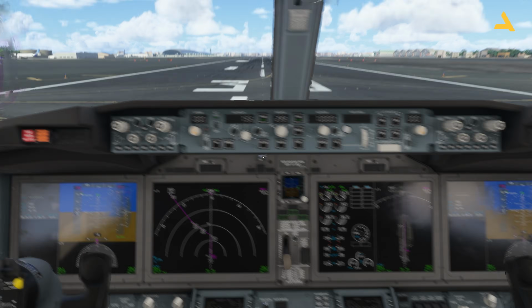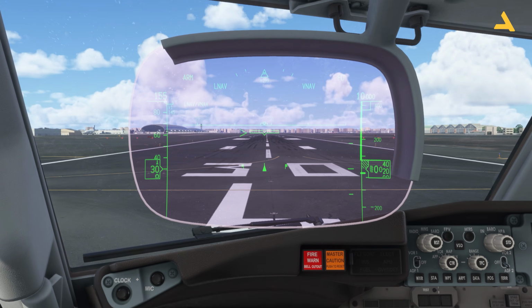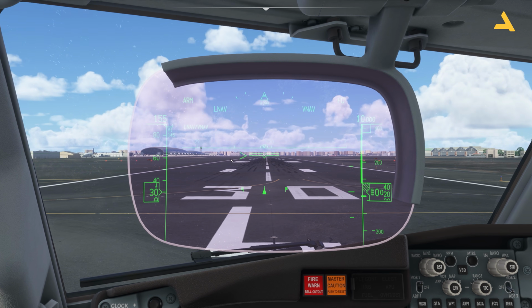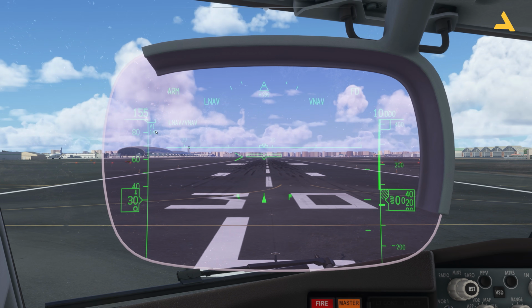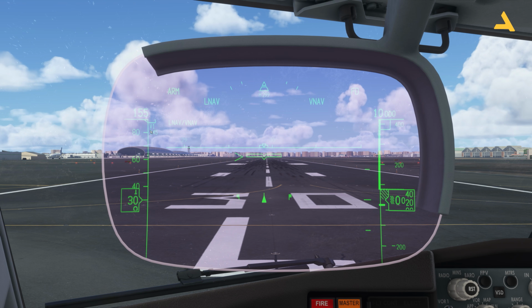That's it. Now you have the speeds over here, although I can also show you over here. I think it's clear. So V1 is 145 knots. This is the decision speed. Before this, you can stop. Otherwise, you have to take off. And the rotate speed is 146 knots. And 155 knots is the speed at which you can just fly without one engine. You can still fly with one engine. So I will be aiming for this speed.